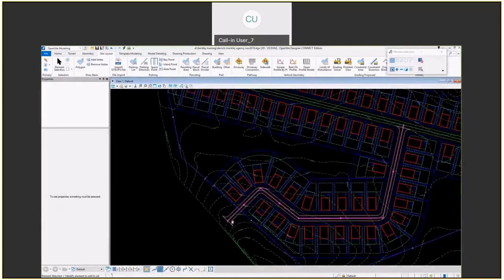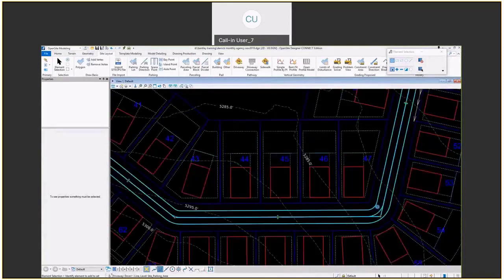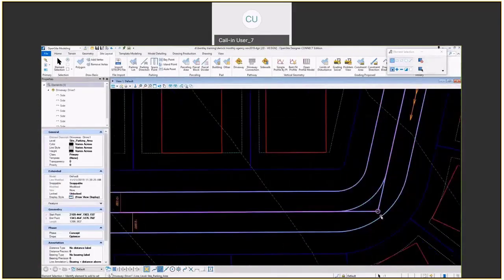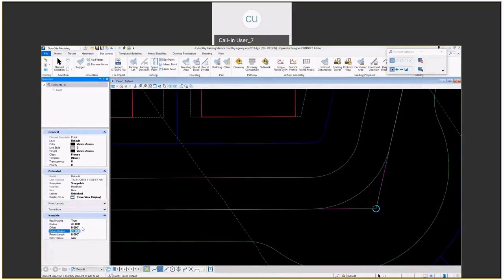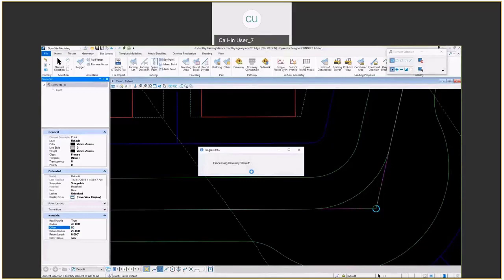If I want to go over to the corner, this area, change the radius, click on the roadway, just make it catch up. I did a little bit of testing this morning, so we'll add a knuckle to this. Add a quick knuckle. Then how big is it? What's the offset? Again, this is back to the user to control what we want to do with this. I just want to come in and put a 50-foot offset.